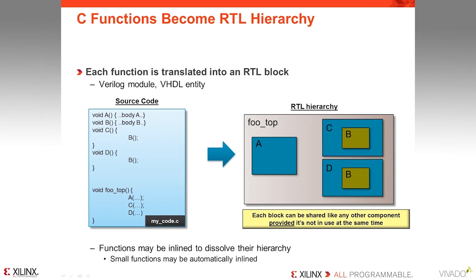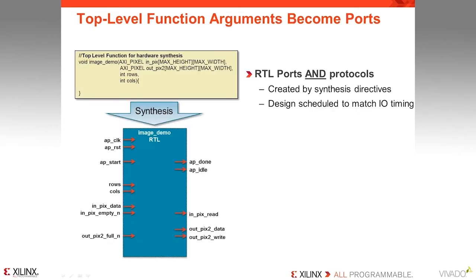Now, these blocks can also be shared, provided they're not being used at the same time. They can also be inlined, and like RTL, you can dissolve that hierarchy automatically. Like RTL, the advantages of dissolving the hierarchy are that we can do more optimization. The disadvantages are we then have more operators to work with, and so runtime may slow down. But that's essentially how functions are synthesized. The other thing we looked at are the arguments to the top-level functions.